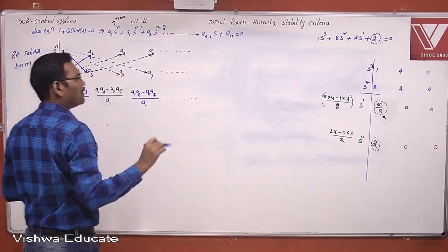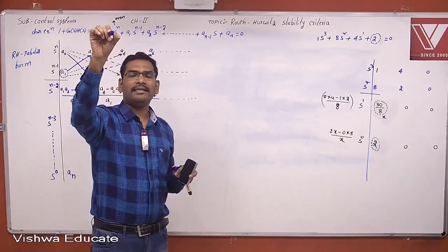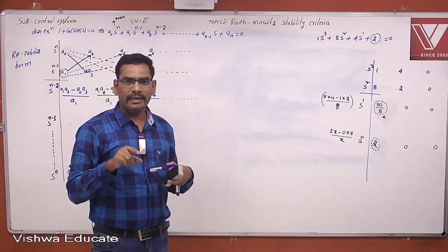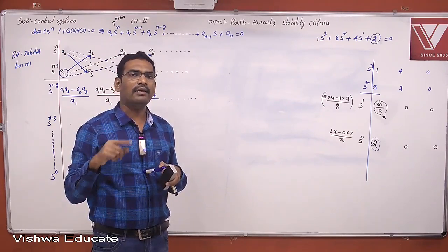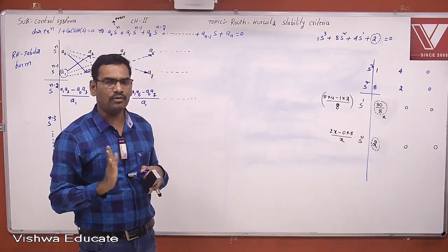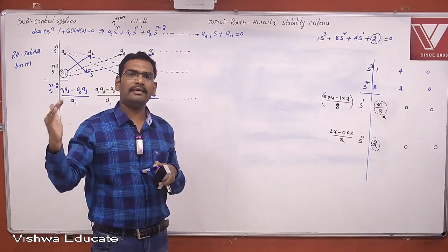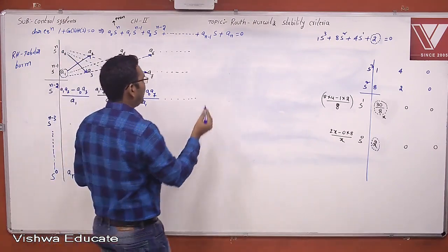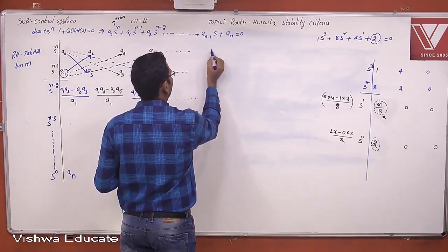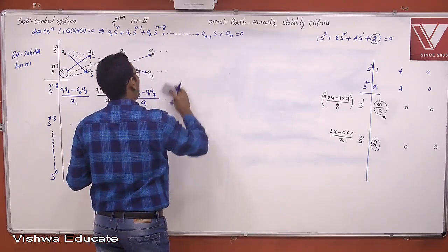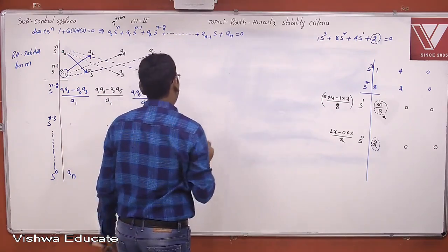Now first you finish this Routh Hurwitz tabular form from the highest power to the least power and calculate all the coefficients. For any row you calculate, the top row is the reference row and its first element is the reference element. Use the up arrow, down arrow symbol and extend those arrows to the next column. Once you finish this, the stability is decided by the first column. So see the first column coefficients, and there are 2 points you have to identify.